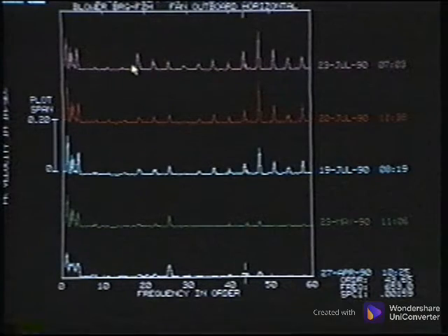If we had been banking on the amplitude of the primary outer race frequency to show the severity, this bearing could have failed before an alarm was triggered. The second, third, and even fourth harmonic are negligible in amplitude. If we had collected the spectral data to only 20 times turning speed, we would have missed the bearing defect.